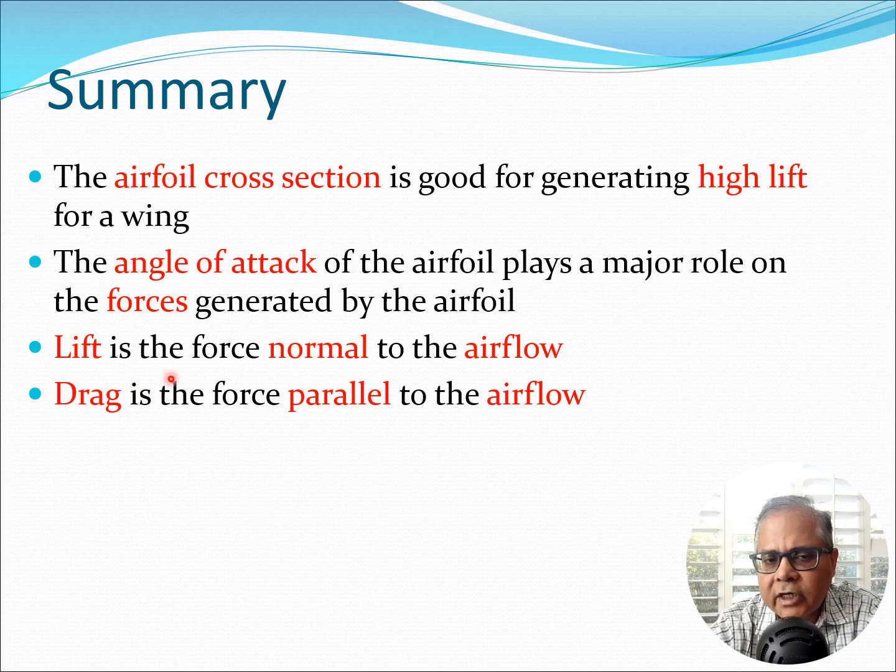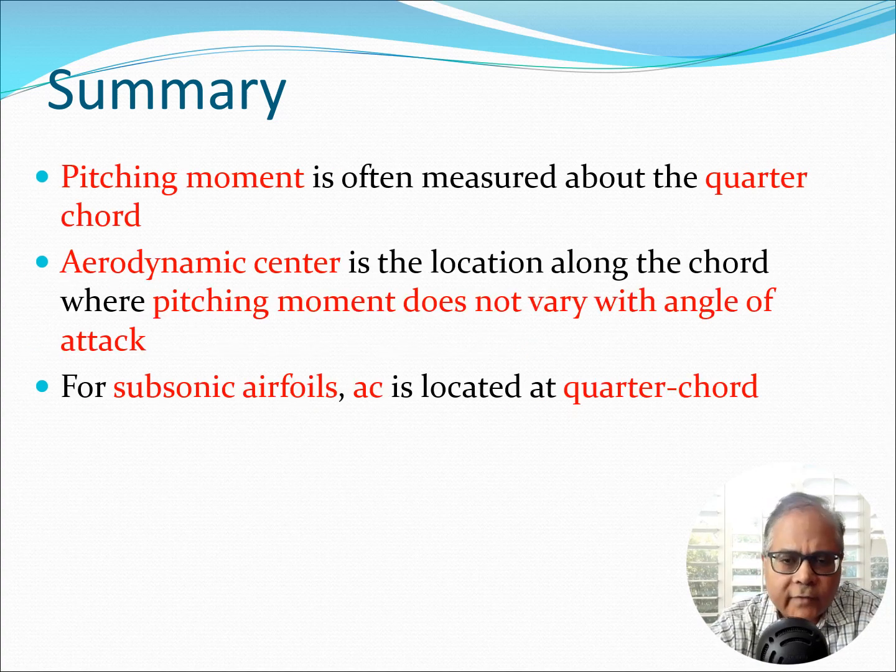Now, we also saw that lift is a force which is normal to the airflow. That was very important. So it is perpendicular to the direction of the velocity, and drag is a force which is parallel to the airflow. Both lift and drag are forces, so we can express them in Newtons. Further continuing on our summary, we saw that there is a pitching moment which essentially tries to pitch the airfoil section downward or upward, and this is typically measured about the quarter chord. It could also be measured at the leading edge or at any given point, but quarter chord is often used.